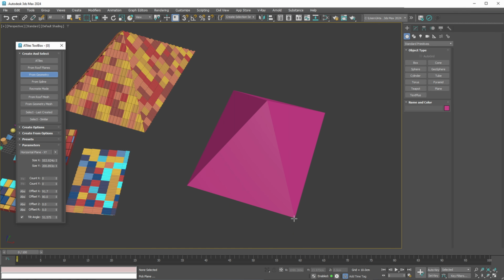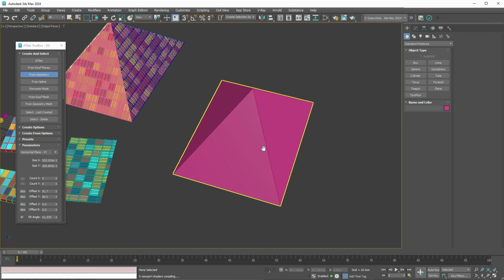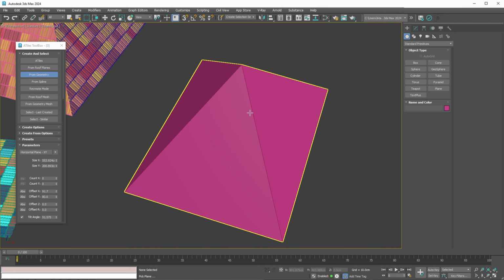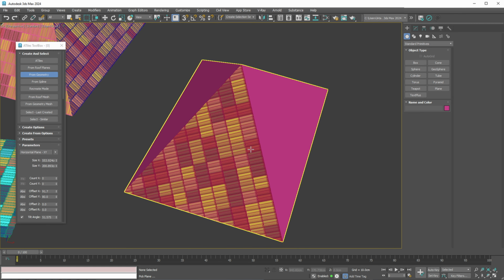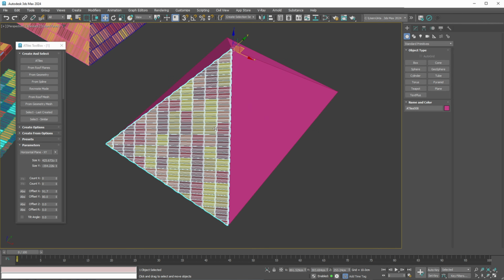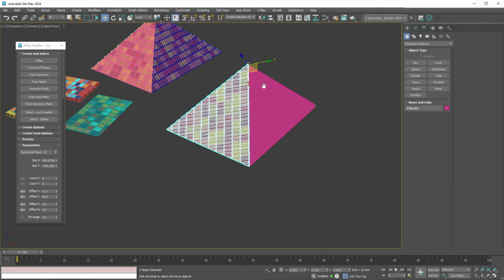For instance, by selecting a point closest to a specific edge, your roof tiles will use that edge as baseline, aligning differently from the horizontal orientation seen before. The placement of new objects starts from the vertex closest to your selection point. Selecting a different point in the polygon could lead to the object extending from the opposite direction.